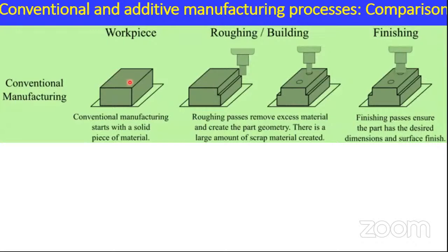Then we need to hold it using appropriate fixtures and jigs so as to accomplish the machining process, and then subsequently get material removal, like in the form of steps, and we might also introduce some blind holes or through holes, leading to an end use part, or it might go into sub assemblies in a complete end use application, right?